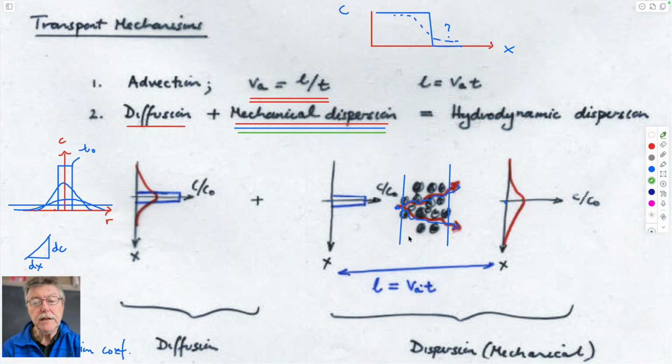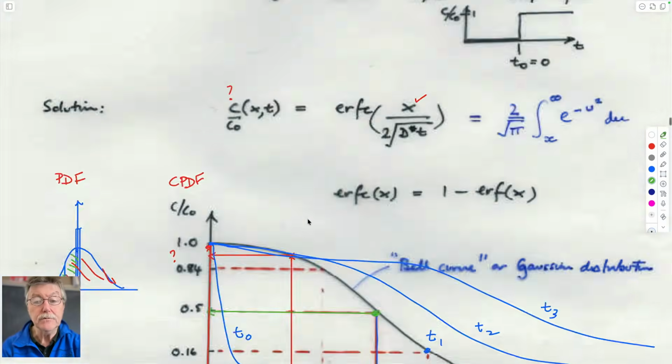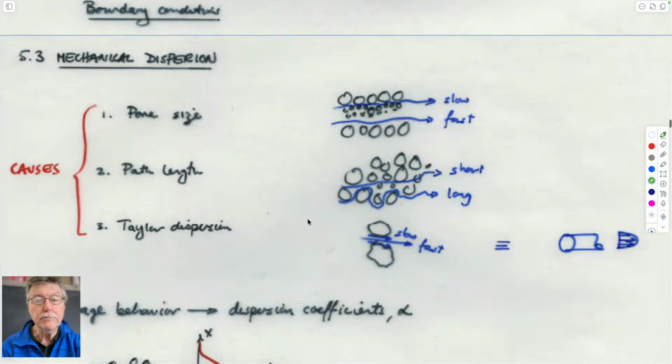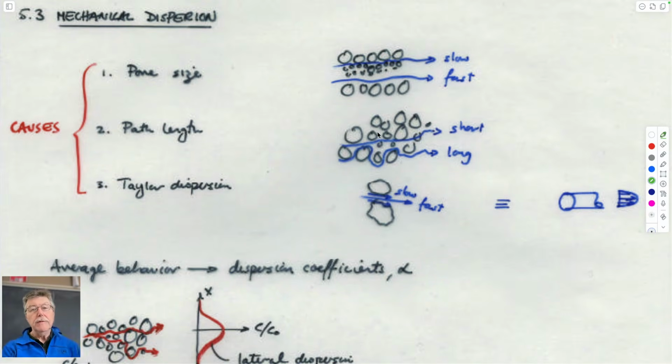And so we want to be able to characterize this effect of mechanical dispersion, so we should understand what drives it. Pretty straightforward. You could imagine that three mechanisms might contribute. One is if you have superhighways with open pores, and it can go very quickly downstream versus very slowly downstream, then this dissolved component would arrive downstream much earlier than that one, and therefore there'd be a separation between them, so it's spread out. If it's going on a path which is different between different molecules that start off here, you'd also think it's spread out, like our little diagram showed.